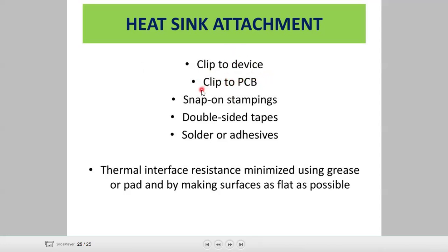Clip to device, clip to PCB, snap and stampings, double-sided tapes, solder or adhesives. So thermal interface resistance is minimized using grease or pad and by making surfaces as flat as possible. Okay, that we will see.